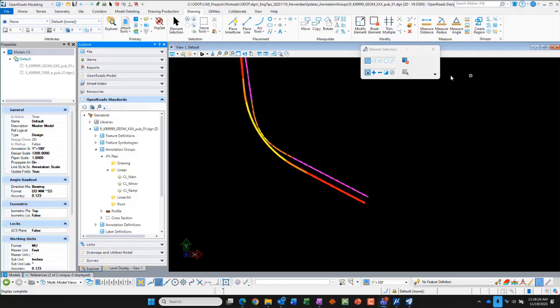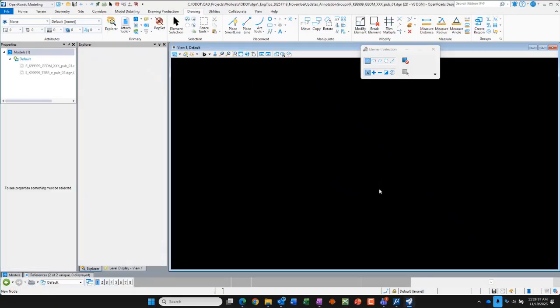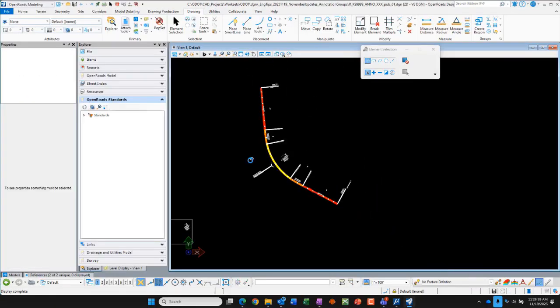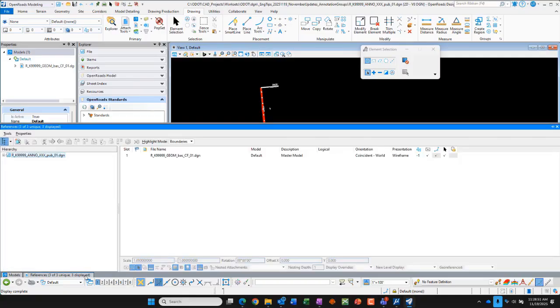And that's the other thing. What Lenny showed here is kind of what I'll call the roadway design workflow. Roadway design does that so that they're not always updating, because every time you open the geometry file, it looks at the annotation and wants to update it. So if you separate your files, you can save some of those headaches.